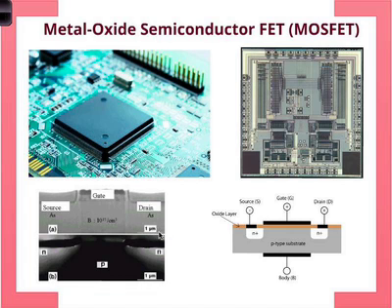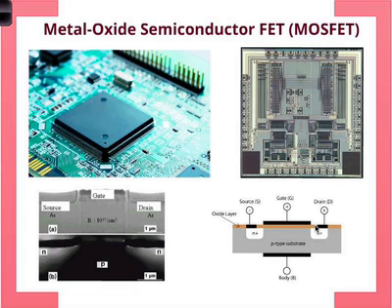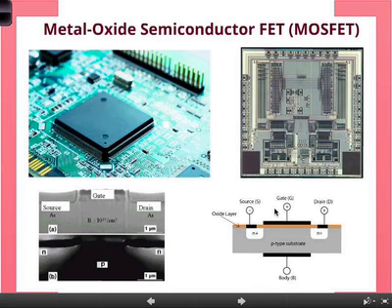Okay, now the difference becomes apparent if you look over here. So what's the same? Let's go through what's similar. You have a P-type substrate. Then you have an N+ region, and then you have a metal contact to the source. So from the source, N+P, you have a PN junction there. On the other side, the same thing. It's symmetric. So you have a drain, N+P. You have another PN junction there.